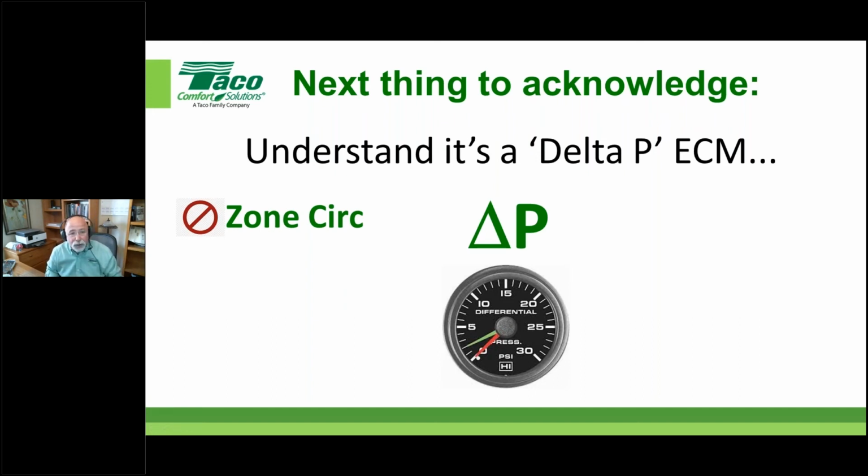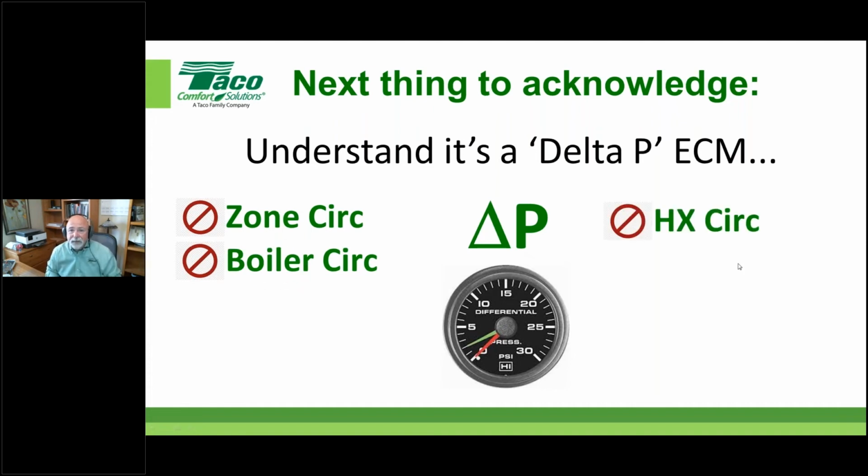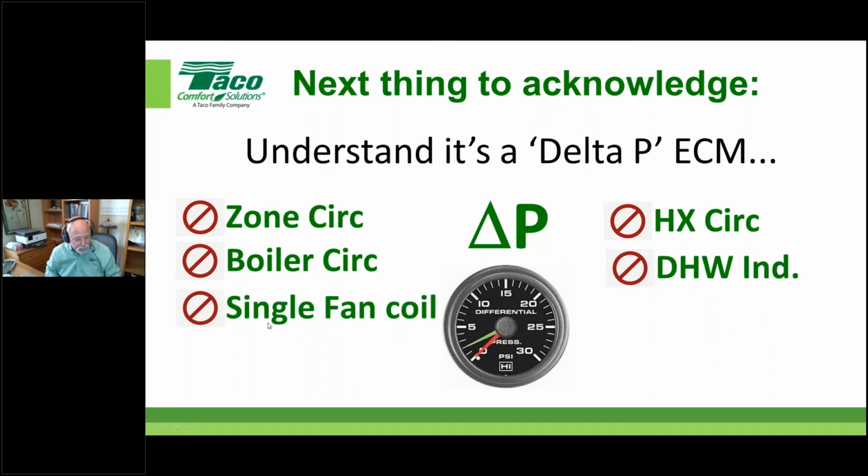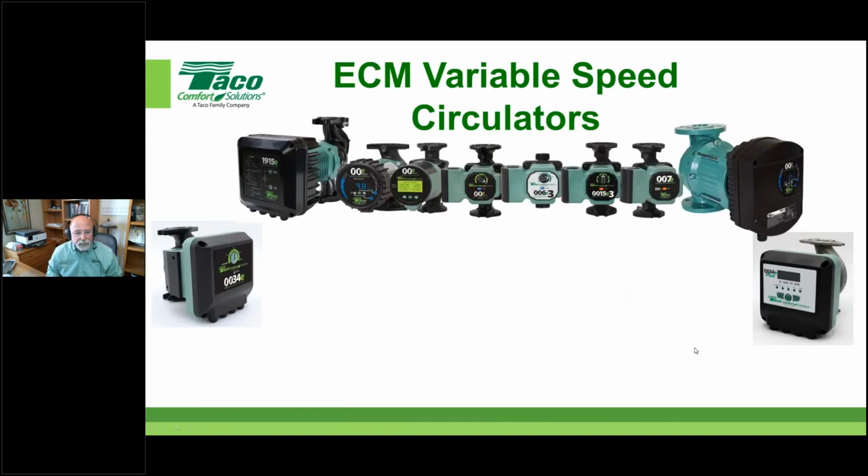And like I've already showed you, zone pump applications, boiler circulators, heat exchangers or domestic hot water indirects. I've kind of indicated that already. What's another couple? Single fan coils with pumps on them, like little zone pumps for coils. Again, you take those modes that are automatic, pull them out of there, and put them in a more appropriate mode.